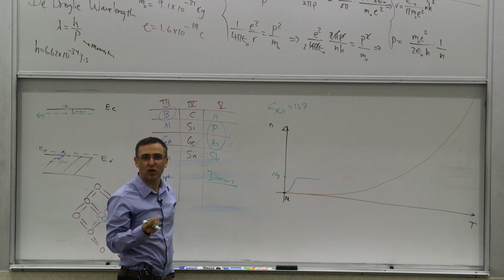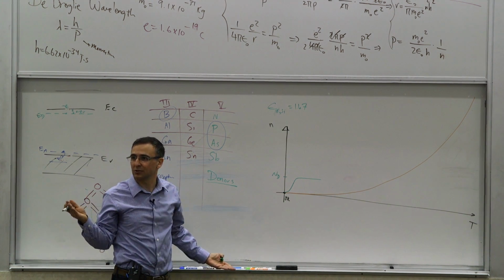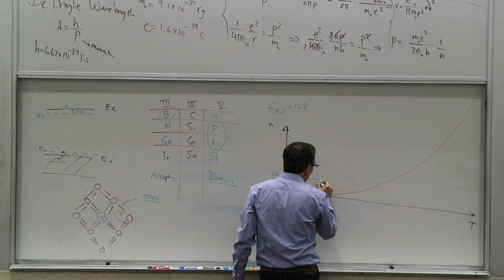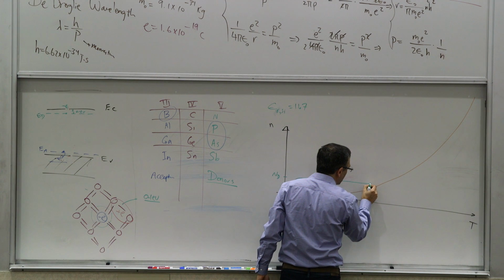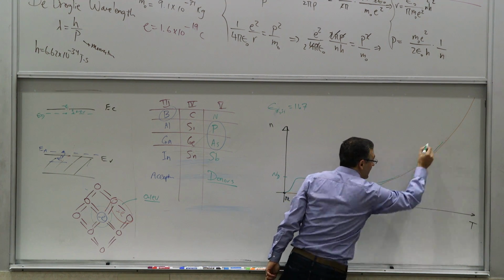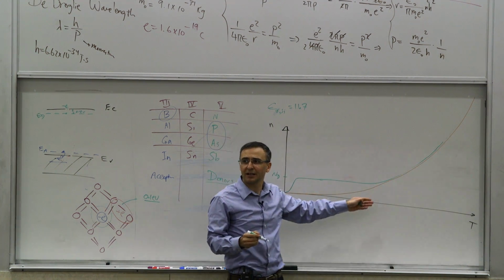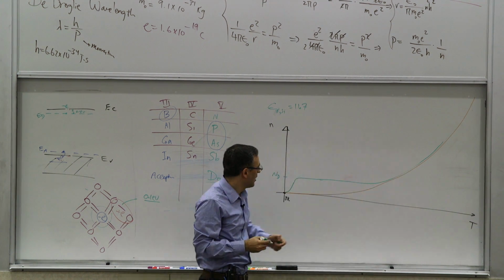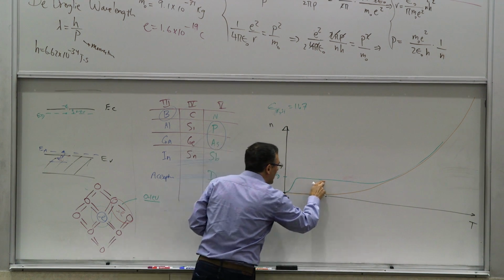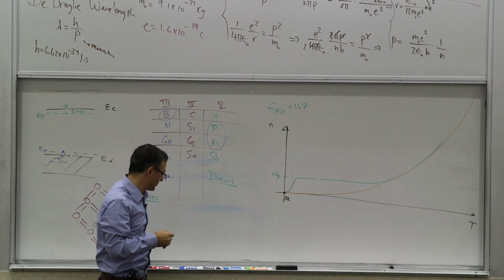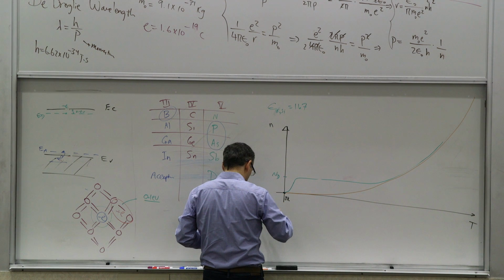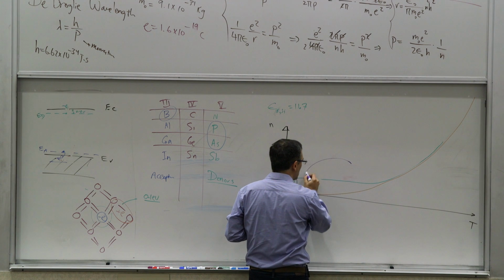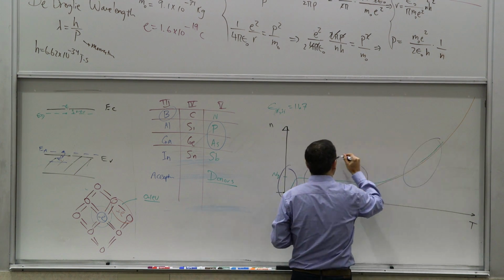And this would be basically ND. The number of electrons would be equal to the number of dopants that you have introduced, because they're all ionized, and that's it. And then how long will this last? Once you get close to this, the thermally generated electron hole pairs would come in, and they would basically be dominating it. So if I ask you, what is a good place to operate, let's define 3 regions. Region 1, region 2, and region 3.